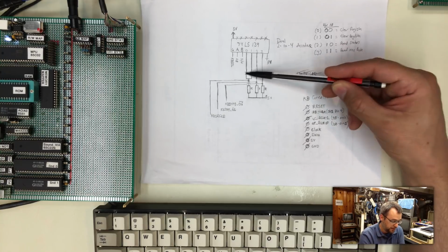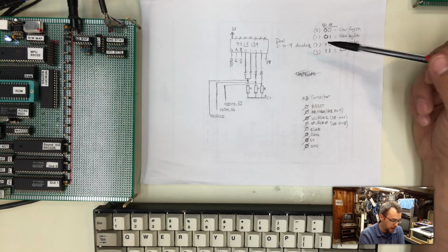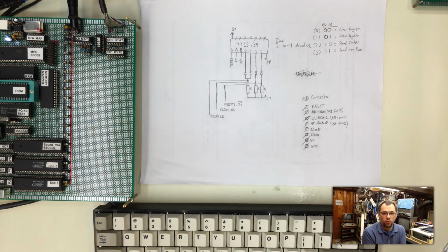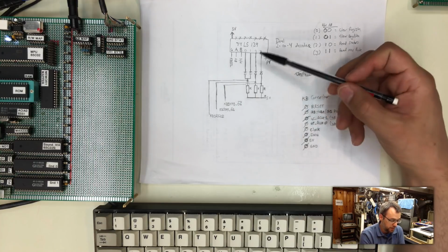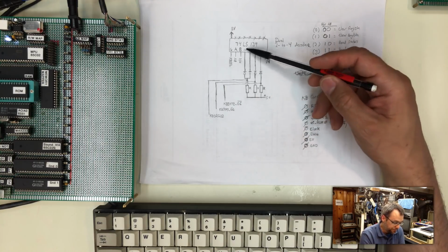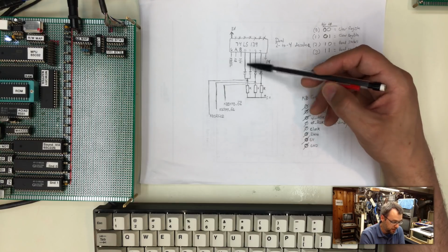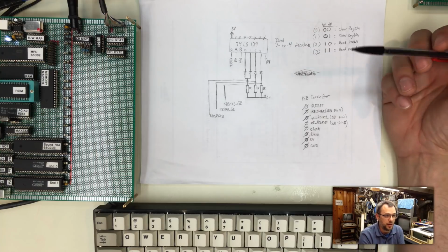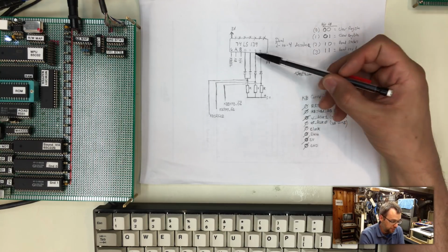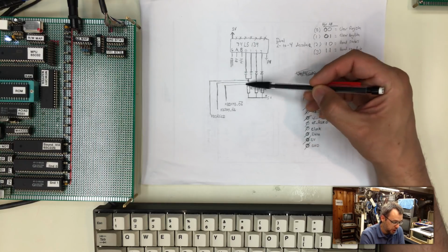Now let's take a look at this part of the logic right here. This part effectively acts kind of like a ROM for us. It's a little bit of ROM encoder logic combined with this. So with the diode selected here on this part, it makes sense. That means it kind of acts as an OR circuit. If either one of these two are selected, it will bring this line low.